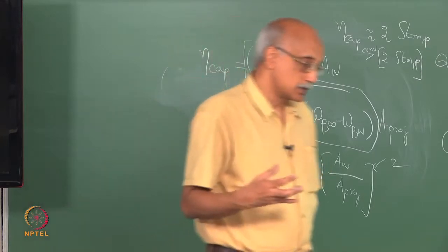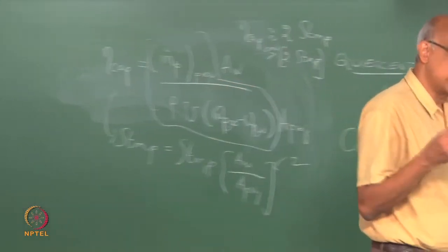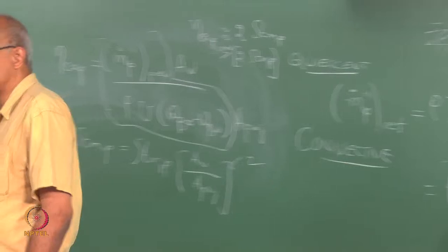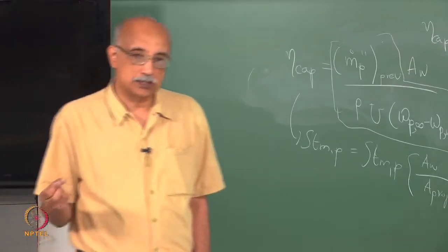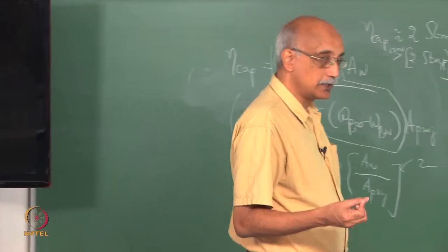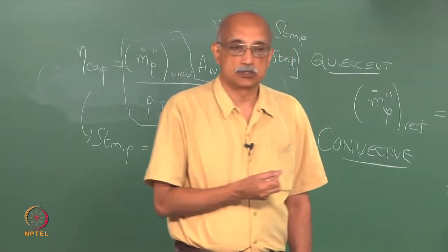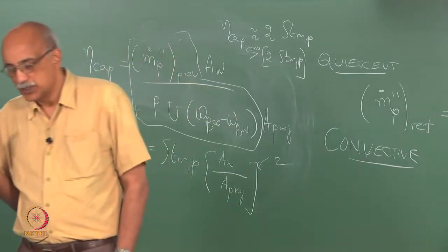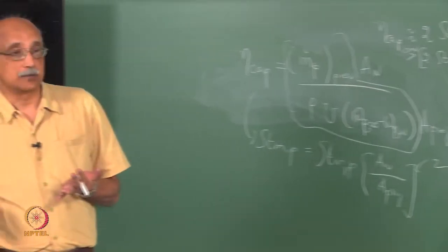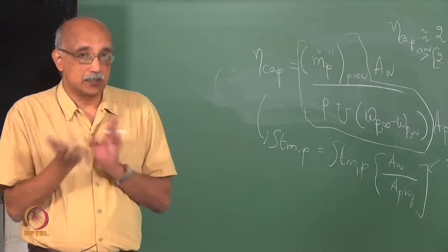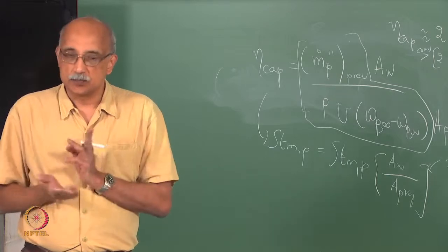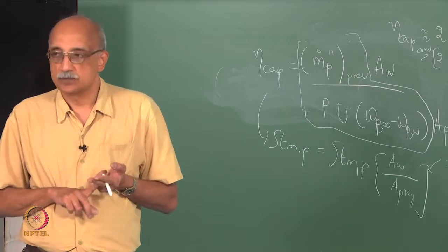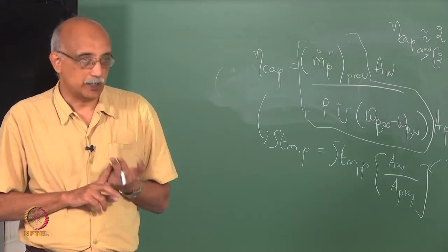The argument goes that in flow situations where the mechanism for particle or mass transfer is the same as the mechanism for heat transfer, then any correlations that you develop using heat transfer data are equally applicable to the mass transfer process that is happening. So, what is the implicit assumption here? That the mechanisms are the same, that mass transfer is happening by the same mechanisms as heat transfer. When is that possible? That is possible when diffusion and convection are the dominant transport mechanisms.